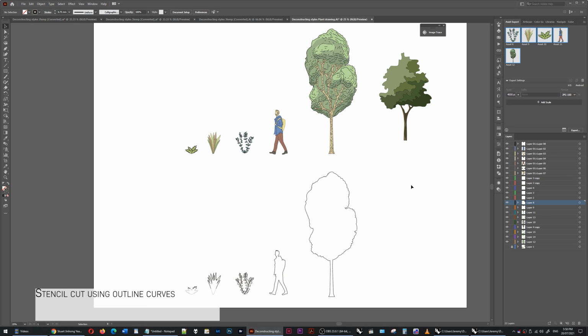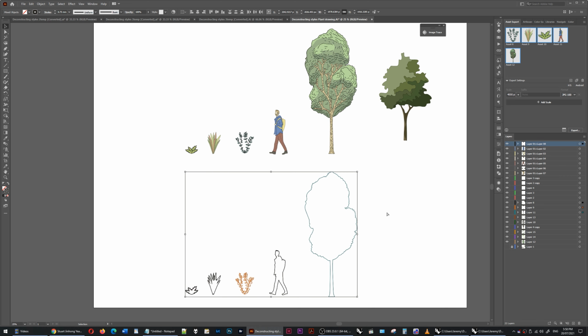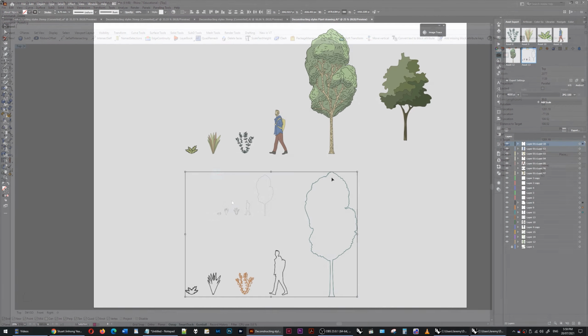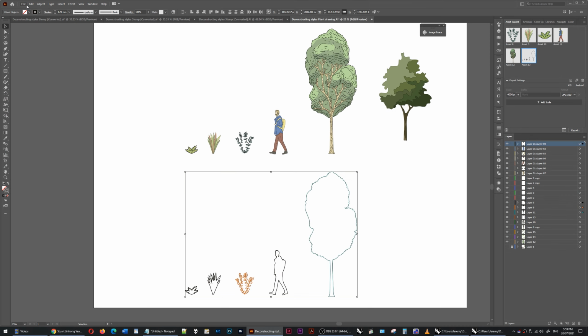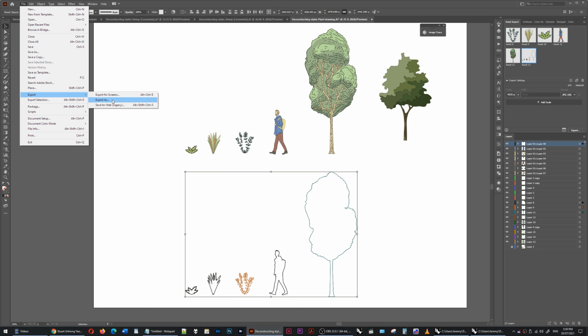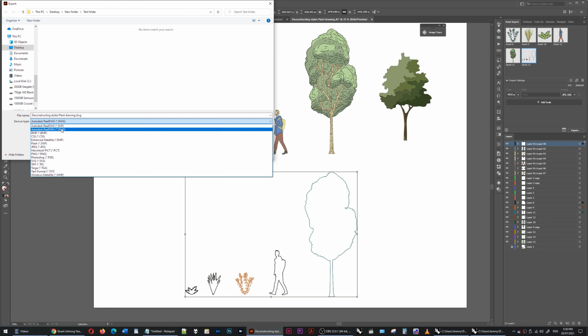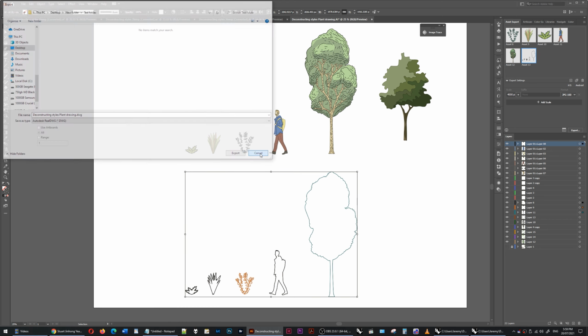If you're using Rhino 7, you can simply copy curves from Illustrator to Rhino as SVG graphics, Control-C, Control-V. If you're not using Rhino 7, you can go to File, Export, Export As, and the formats DXF, DWG, SVG and PDF Rhino can import as vector graphics.